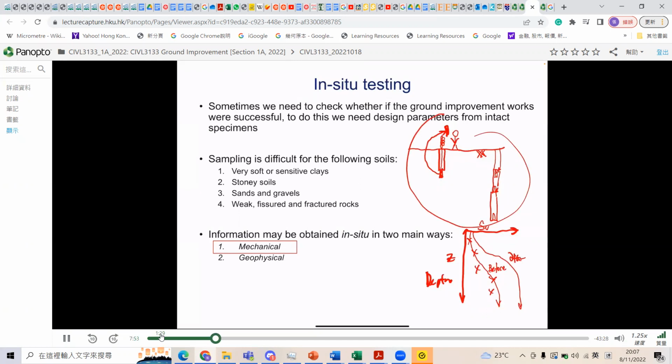And likewise, it's difficult for sand and gravel to be transported in terms of intact samples. What I mean by intact is that when you extract the sample from the ground, they remain coherent enough for testing. Clay with high cohesive properties can be transported, cut, and placed in a triaxial specimen odometer test. But you can imagine that granular materials, as you remove, will just collapse to the angle of repose. Likewise, it's not easy to break off relatively strong fractured rock material and bring it to the lab.